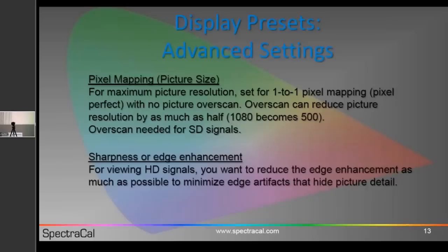So it looks like in this particular case, the default setting of 50 was appropriate. In other displays, you need to judge that on a case-by-case basis. Normally, you would adjust the sharpness control to a higher than normal setting in order to view the haloing effects of the edge enhancement, and then set that to minimize the edge enhancement without softening the fine resolution in the picture.